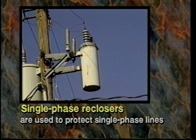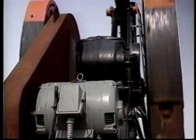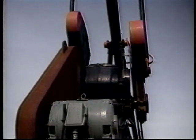Single-phase reclosers are used to protect single-phase lines, such as branches or taps of a three-phase feeder. Three-phase reclosers are used where lockout of all three phases is required for any permanent fault. They are also used to prevent single phasing of three-phase loads, such as large three-phase motors.